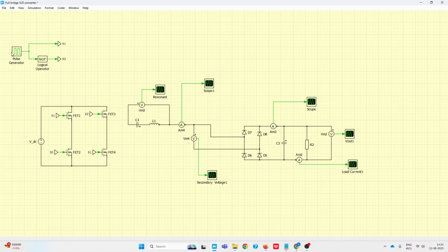Now you see that you don't have to make the simulation complicated with this S1 and S2 block, because when there are Goto and From blocks, what is going to S1 is coming here and here where the tag is S1, and what is going to S2, this Goto block is coming from this From block S2 and S2. Their names should be the same.